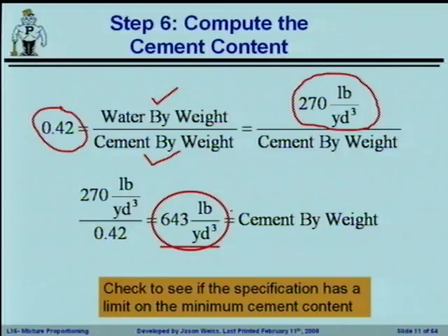Does anyone understand where 564 may come from? Why would we have such an odd number? Bags of cement. Right, it's based on the old bags of cement, and everybody knows that a bag of cement weighs in the lower 90s, 92, 94 pounds, somewhere in that range. Back when cement all weighed the same. Now around the world they're changing the weights because apparently it's illegal in some parts of the world to lift 92 or 94 pounds.